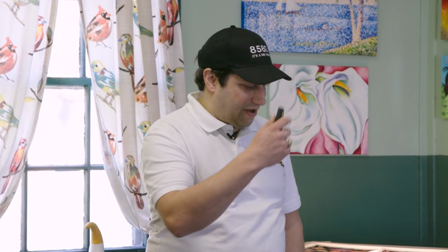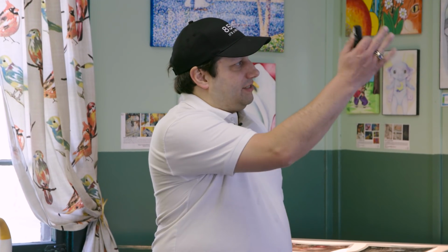What was the wrong capacitor type? Getting to that. Oh, I'm sorry. This guy has a great website. It's all about, and I believe it's a polarized capacitor that's in the audio circuit that he says is the wrong type. And he details on this site what that capacitor is, why it causes the audio to fail, and how to replace it where it is. He talks specifically about the 4000, but he suspects it was probably in the 1000 and just got carried forward to all the rest of the machines.